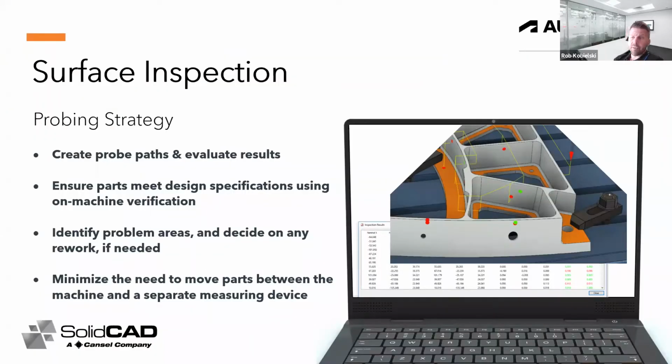Lastly, under this topic of extension, I'll cover on-machine verification, also known as OMV, and this helps users reduce the setup cycle times on CNCs, as well as realize better part quality. Almost all new machines ship with probes, and this is for a good reason. So let's put them into the production cycles.